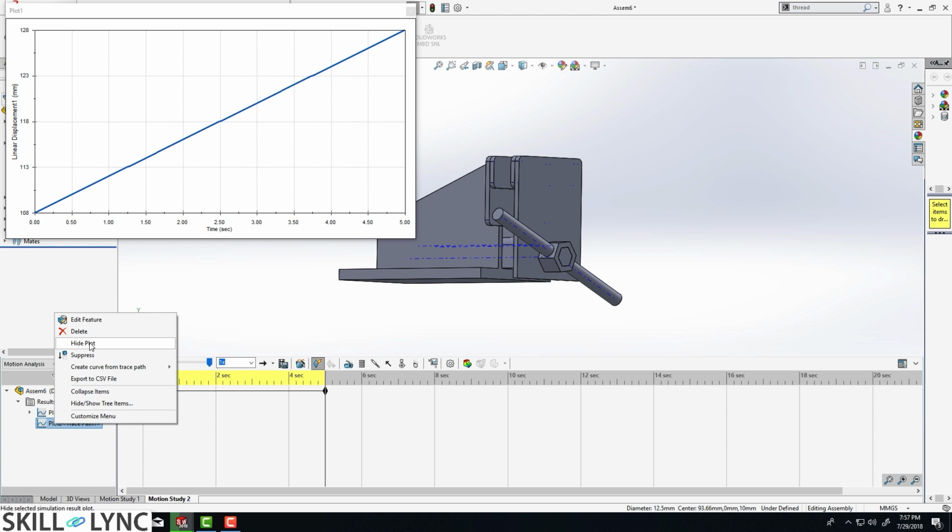Finally, we have the planetary gear. The planetary gear is positioned between the ring gear and the sun gear, and as you can imagine, its rotation axis is going to change. Now, in addition to all these components, you can also have a carrier. A carrier is a component on which all the planetary gears are mounted, and in general you can provide an input power or take output power from either the planetary gear, the ring gear, or the sun gear.